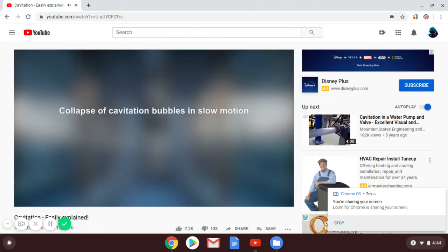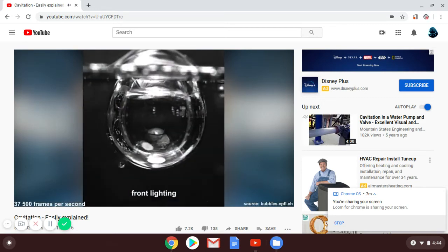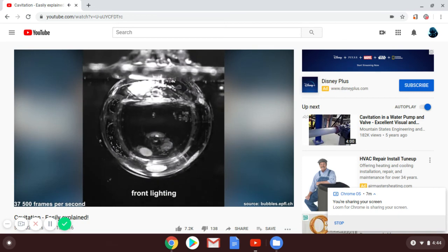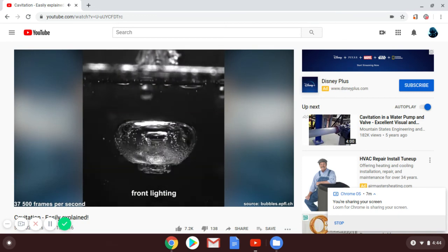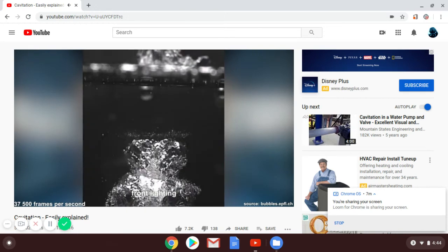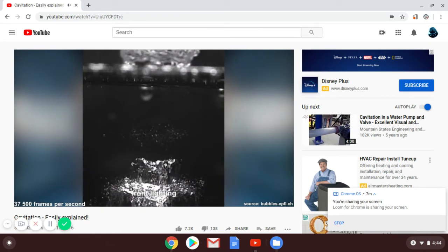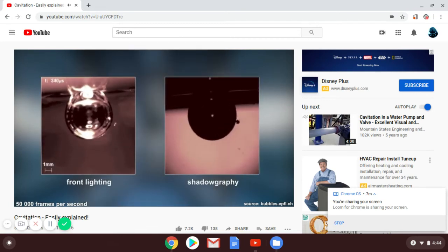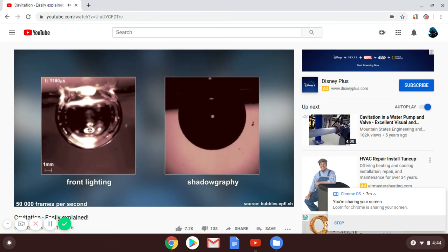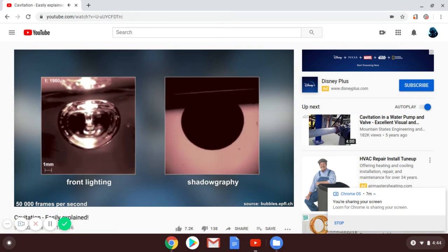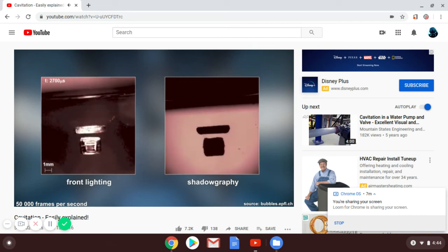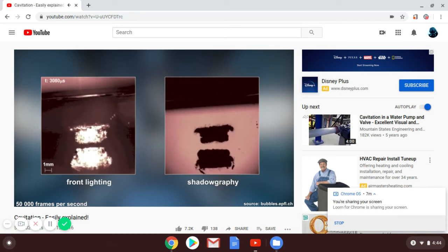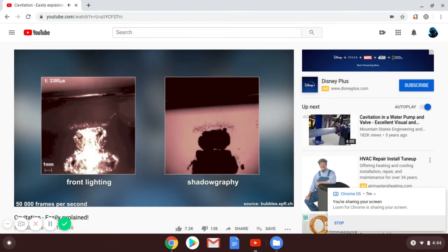But how does it look when cavitation bubbles are formed and collapse in detail? We can see the formation and the collapse of cavitation bubbles with a diameter of approximately 9 millimeters in slow motion. In real time, this process takes about 4 milliseconds, and it is a spectacular physical event. Because liquid water occupies many thousand times less volume than vapor, the bubble implodes. It first assumes a ring shape. Shock waves and a strong microjet are the result of a collapse.